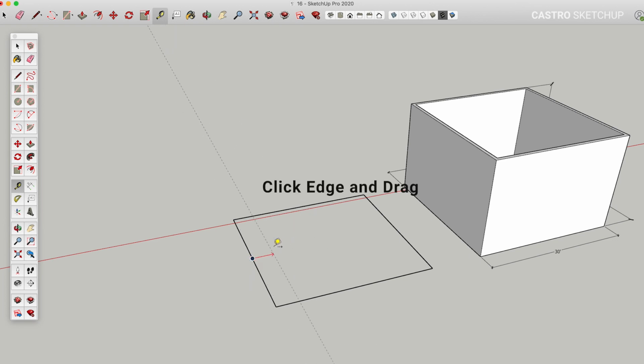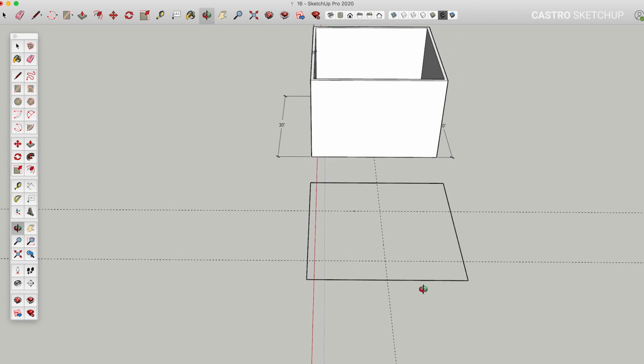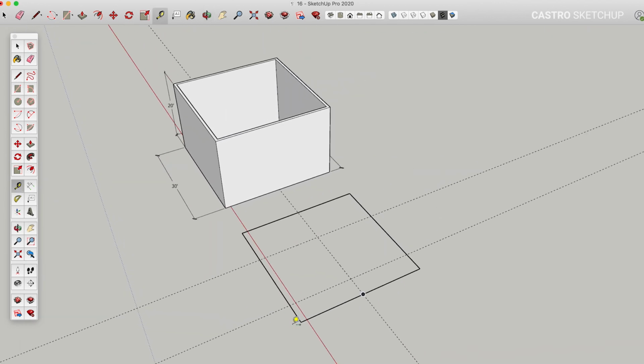Let's say I want this guide to be 5 feet here, right? And then from this wall, there's going to be a bedroom that's 15 feet there. So essentially we could use these guides almost like a rough floor plan or construction lines. So when we're actually modeling, we can just follow and connect the dots.